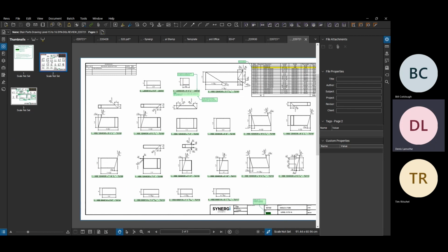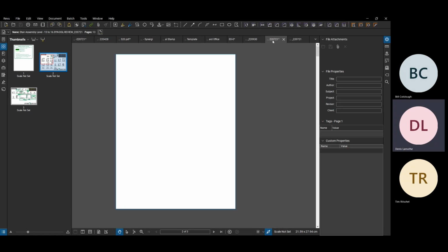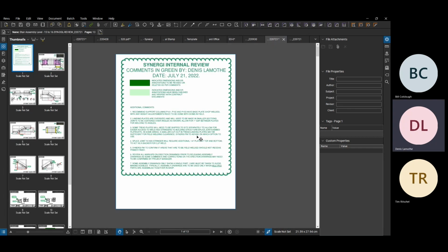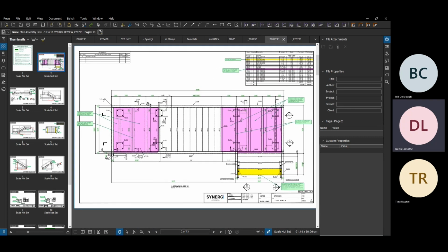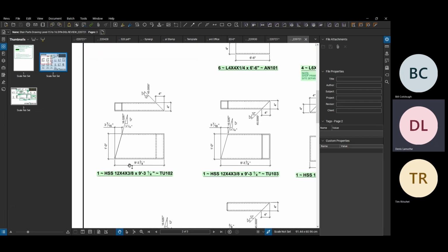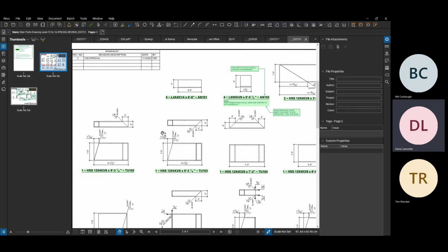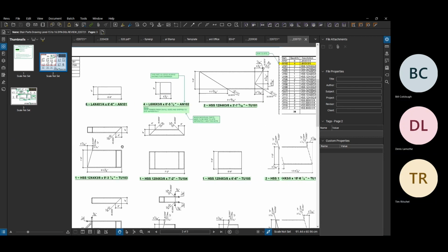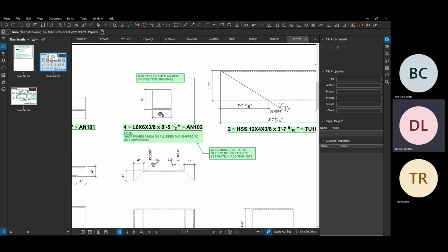The part drawings, the main things that we're checking for here is that the sizes and quantities match what's shown on the assembly drawings. So in order of checking, I typically check erection drawings and the assembly drawings and then the part drawings. Once you're comfortable that the sizes on your assembly drawings are correct, it makes checking the part drawings a little easier. You can double check with what's on the assembly to make sure that the overall lengths and sizes and profiles used match. Again, shouldn't really be an issue in Advance Steel, but you just never know. Maybe the drawing just wasn't updated and they forgot to click on the update detail thing and this angle could have changed to 6 inches long or something.